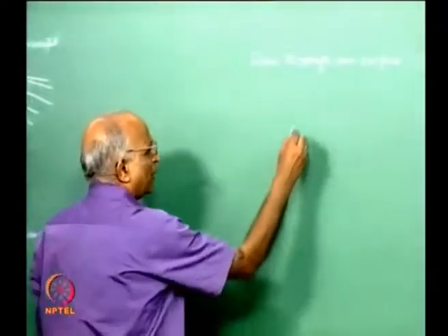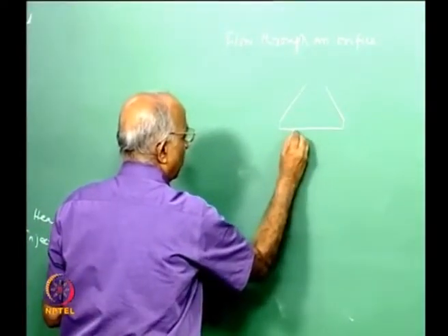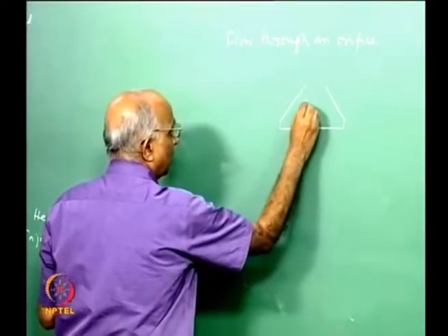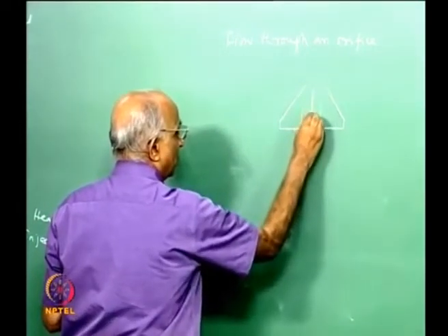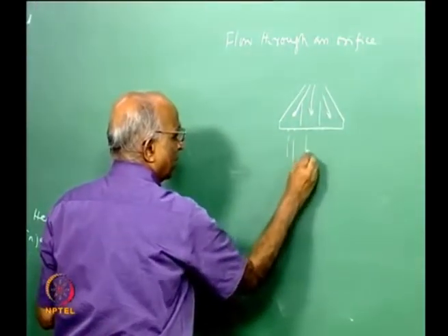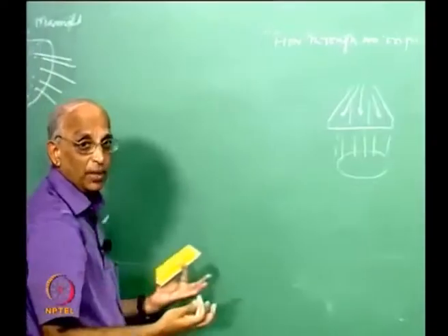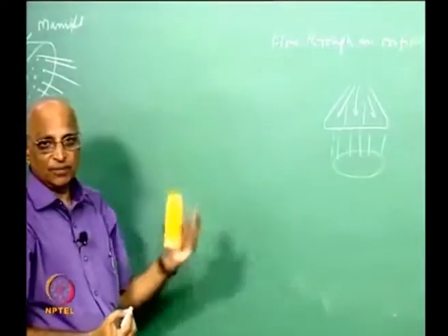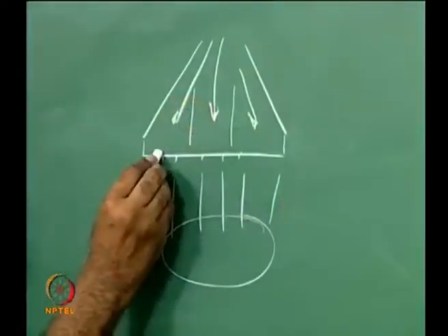But what we can do in a liquid propellant, you have the manifold here, you have the set of orifices here, maybe I could divide it, I could partition it in some way. In some region I admit the fuel, in some region I admit the oxidizer, maybe I admit them like this, I allow them to mix in this region and evaporate and burn. This becomes my shower head injector. How do I find out the flow through the orifices?